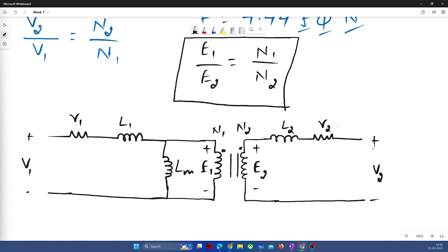Oh, okay, no issue. So you are almost there. Whoever answered that, I think Adesh. LM, the magnetizing inductance, is a way to represent how much flux is required to operate the transformer, right? The transformer will have a certain supply, and since primary and secondary sides are inductively connected, there is no conductive coupling, so there must be some flux that couples both the sides, right?